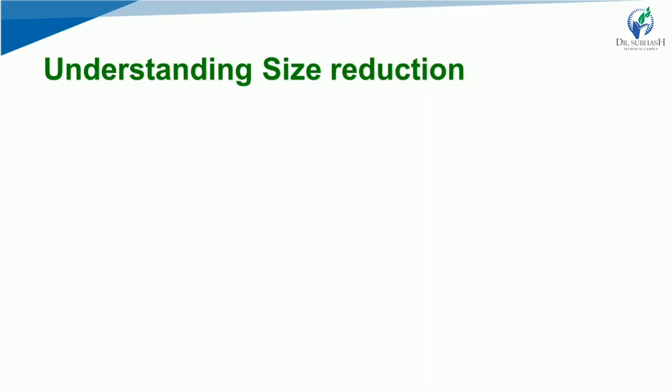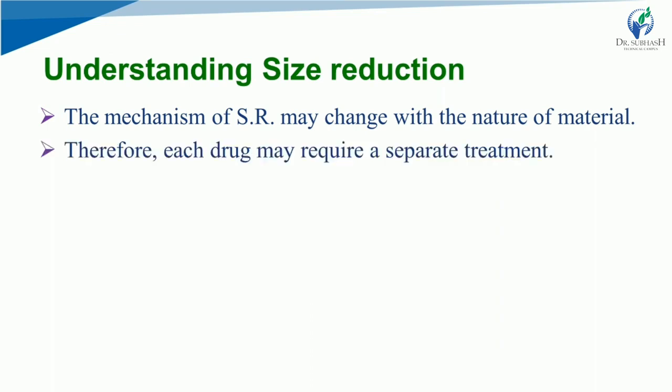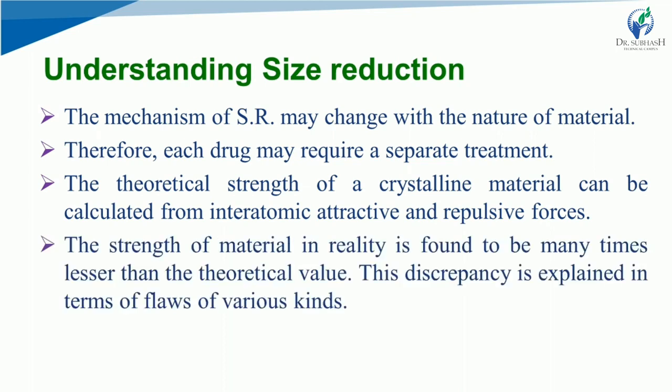Now let us get a little bit deeper understanding of size reduction. The mechanism of size reduction may change with the nature of material. Therefore, each drug may require a separate treatment. The theoretical strength of a crystalline material can be calculated from interatomic attractive and repulsive forces. The strength of material in reality is found to be many times lesser than the theoretical value. This discrepancy is explained in terms of flaws of various kinds.